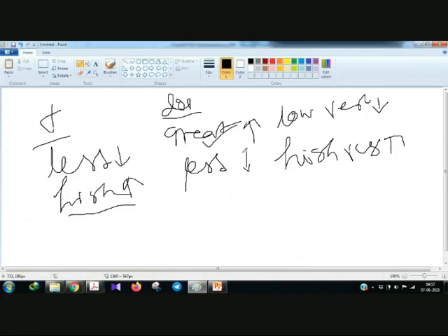But at the water table, there is a high contrast between the upper unsaturated and lower saturated layer, and that is easy to understand. If my sole objective is to find the groundwater table, then I might go for the low resolution case where I can map up to 150 feet.